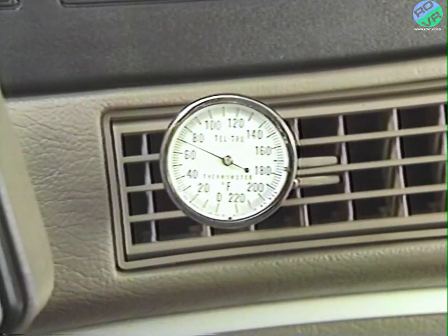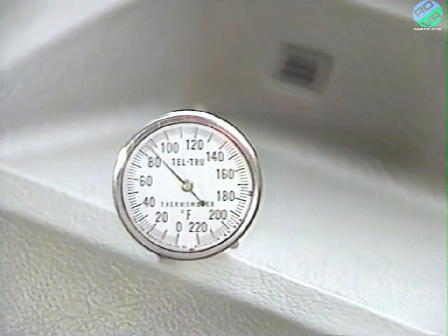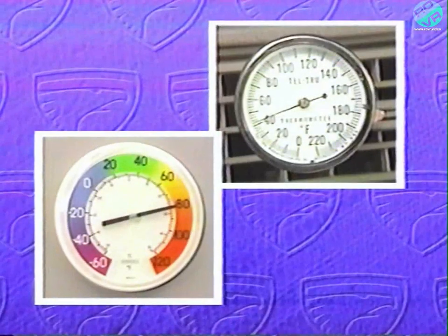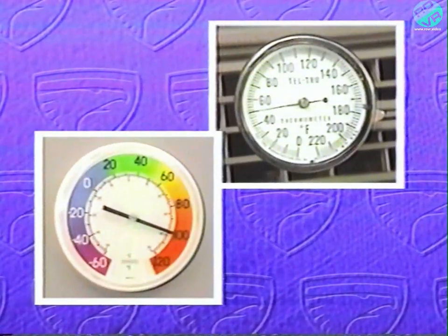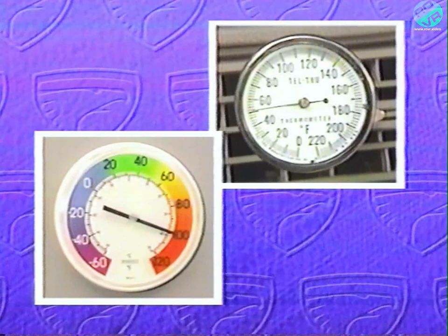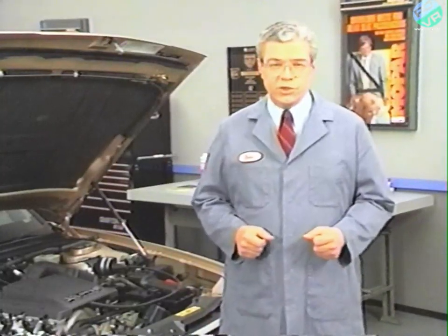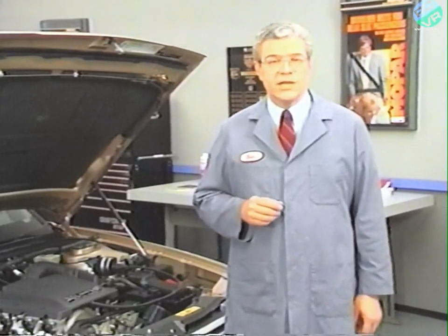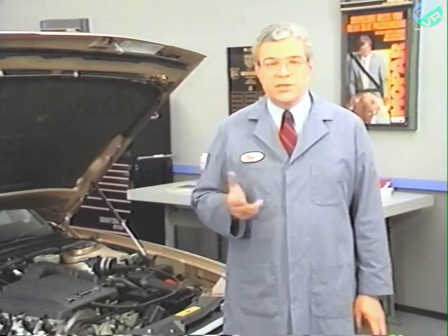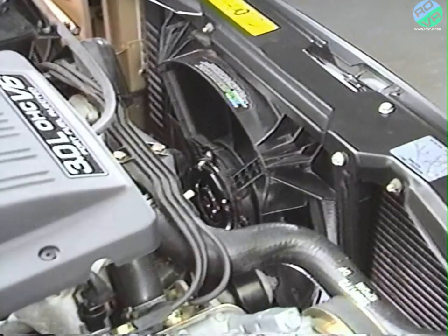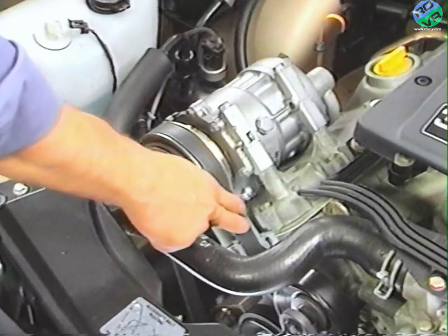For an accurate check, make sure the in-car temperature is high enough to trigger maximum cooling. Also, keep in mind that as ambient temperature and humidity rise, discharge temperature will rise. So your customer shouldn't expect Arctic air from a discharge on the hottest, muggiest day of the year. When dealing with insufficient cooling, don't overlook causes outside of the AC system, such as an engine cooling fan that isn't operating or a loose drive belt.